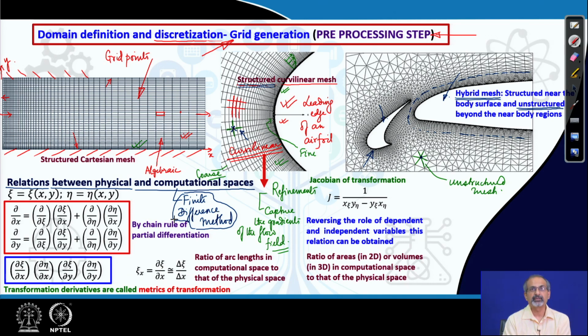While in finite difference method, you try to transform the problem from the physical plane which is curved to a computational plane which is nice and rectangular, let us say, where we have uniform grid spacing. That is why we transform the problem from xy plane to xi eta plane. So, the xi eta plane is basically the transformed plane. When you do that, all the governing equations have to be transformed as well. So, you have seen that in governing equations we have derivatives, partial derivatives with respect to x, y and so on.